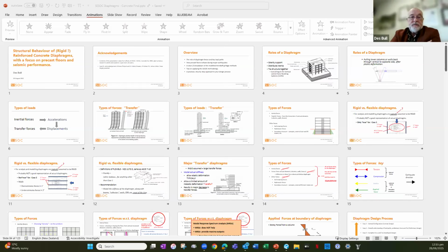Well, fundamentally, particularly with the modern solutions that Reids have been developing, it's a pretty good option. The new Reid couplers and inserts are good options. The only thing I'm saying, and I'm pretty sure Reids are all over this, but we do this anyway: the embedded length depth, we run a Chapter 17 3101 check to make sure that for shallow embedded item pull out, pry out has been met by the dimensions of the item, whether it's Reid's or anyone else's. We just run a quick Chapter 17 check.